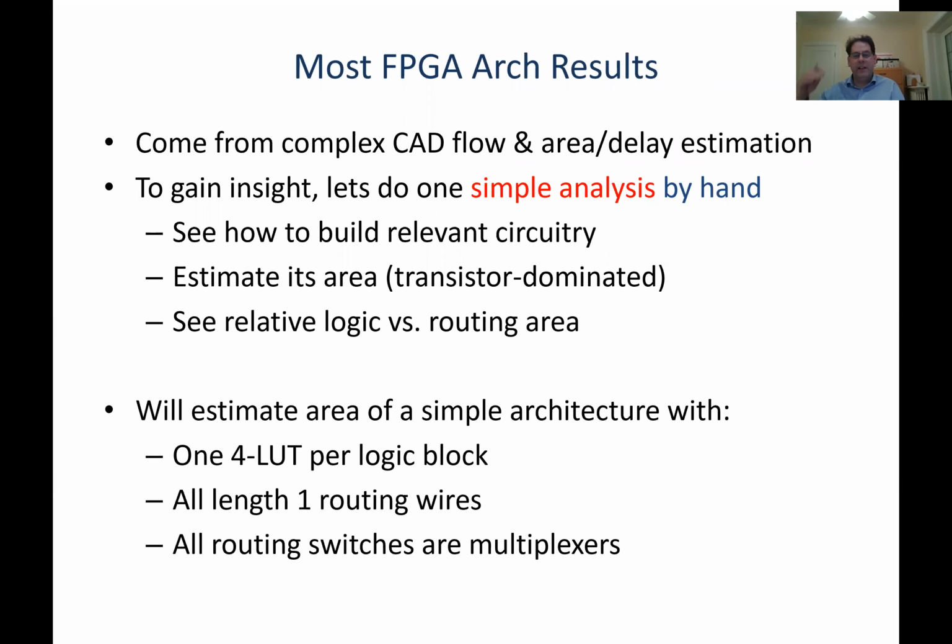You basically can't model most of this stuff analytically. So if you really want to know whether this particular idea is better than that idea, you actually have to do what was in this week's reading: build an entire CAD flow, run a bunch of benchmark circuits through it, estimate area and delay in a bunch of different chips, and see what the trends are. And we will go through a bunch of papers that have done exactly that.